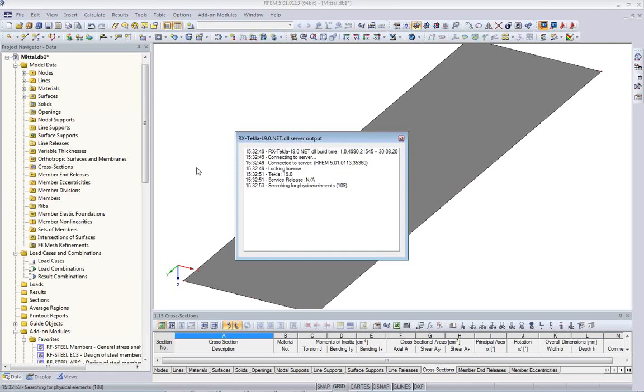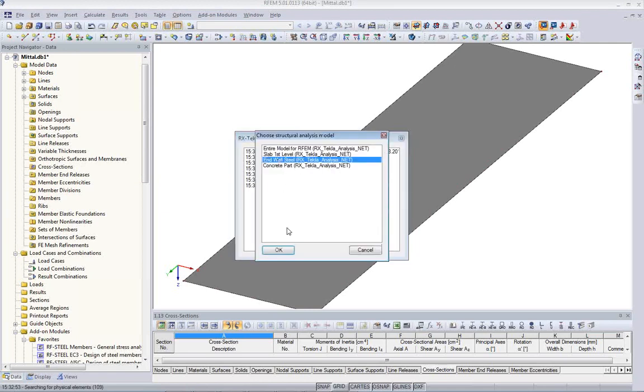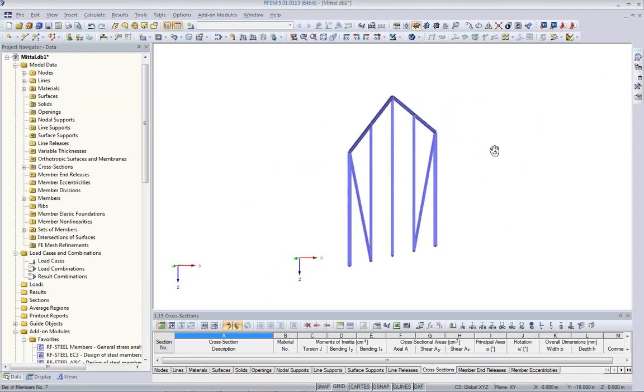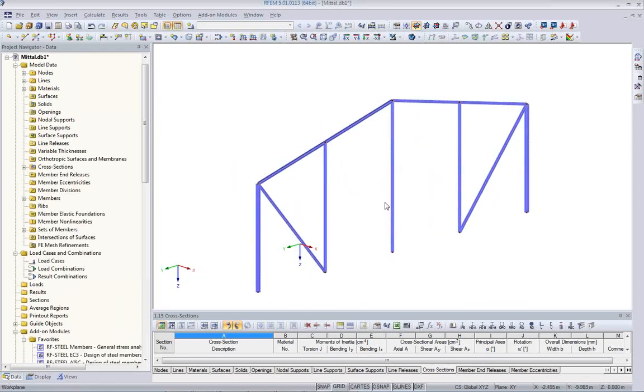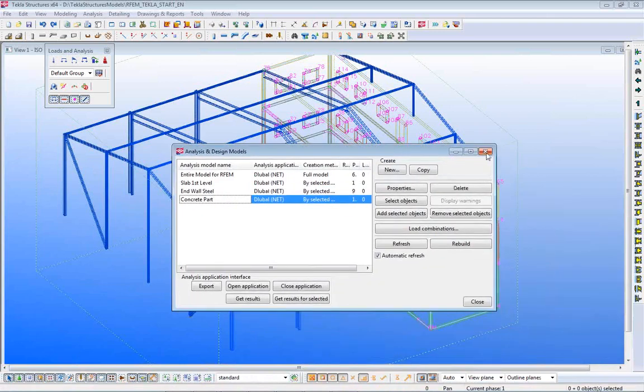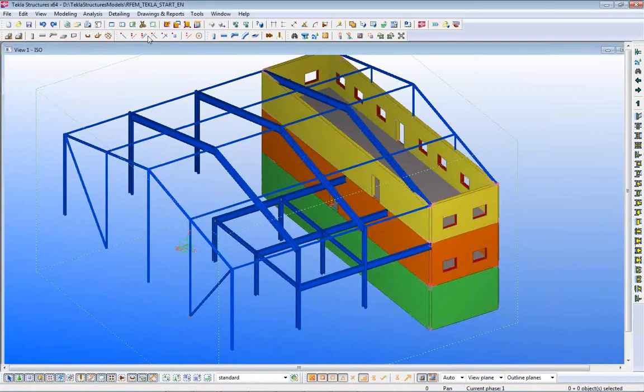And also the same way I can say I want to have only one end wall, and I do like a 2D analysis of this end wall here, for example. If you want to, you can import only one beam if you want to. Please note, here's two analytical members. Inside Tekla, we have one part. When I update it later, it will be staying one part inside Tekla. Okay, but actually I want to have the entire model.